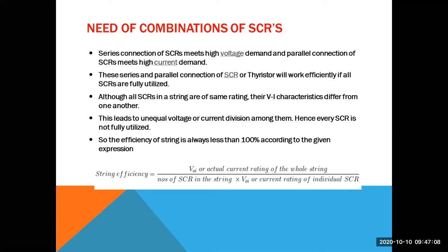For the same example which we discussed, if we calculate the string efficiency, we consider 10 volts for each SCR, and we are using 10 SCRs to meet 100 volts. That is the same example. If you apply the string efficiency, it becomes 100% efficiency.